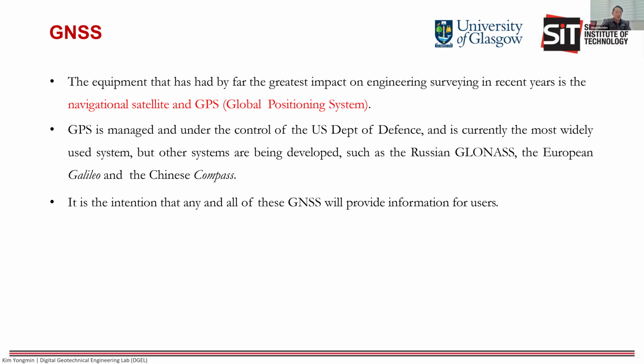They offer precise control and mapping, and specifically in Singapore, we use the RTK GNSS for centimeter level accuracy. When you combine GNSS with total stations, you actually get very accurate and precise results. So it's this kind of combination of technologies that modern surveyors achieve speed and reliability across large and quite complex work sites.